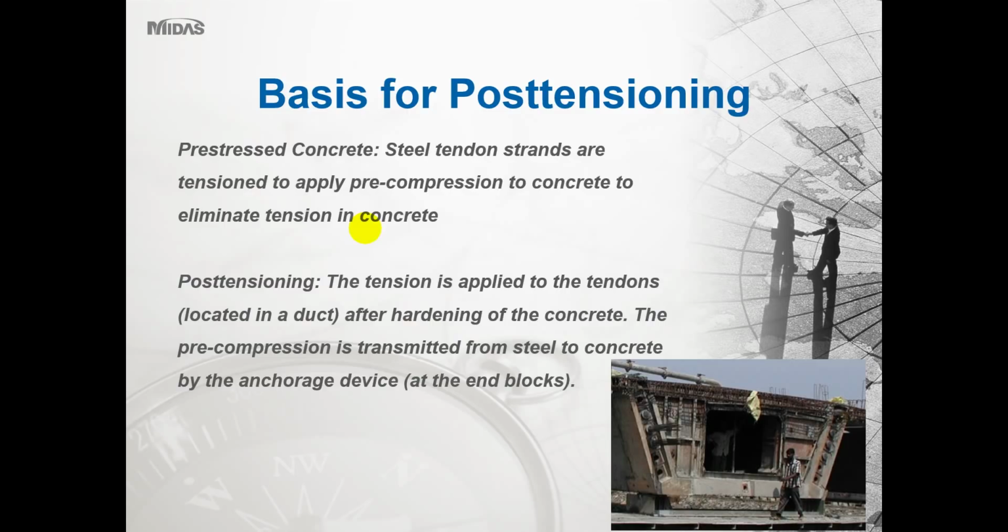So pretensioning, which is where the pre-stressing tendons are applied before the concrete is cast, is commonly used for precast beam bridges like M, Y, TY, U beams, and things like that. Most often these tendons are straight tendons, and the bridges are mostly single span bridges with span lengths ranging up to about 20 meters at a maximum.